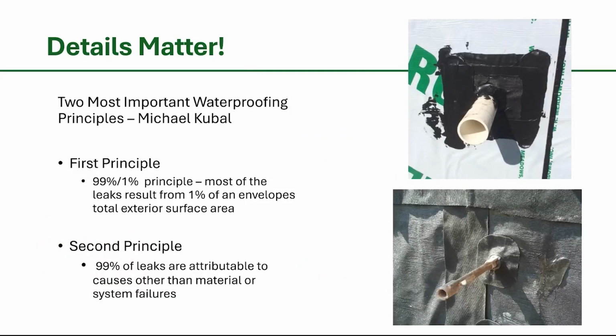Details matter. Again, penetrations, pipe penetrations. The upper penetration has a finger flashing on it and is covered up with another piece of membrane and then a building envelope mastic. We put the finger flashing on there to connect it up to the membrane behind it to distribute stress. There's a lot of stress that can be placed on a pipe. It might move differentially from the actual building. The plumber might come and have to wrestle with that pipe to try and connect up a new system to it. If it doesn't have a robust connection that can distribute those forces back out onto the membrane and stay as a system, you can have a potential point of failure there.